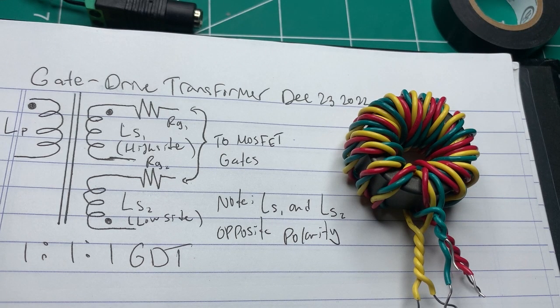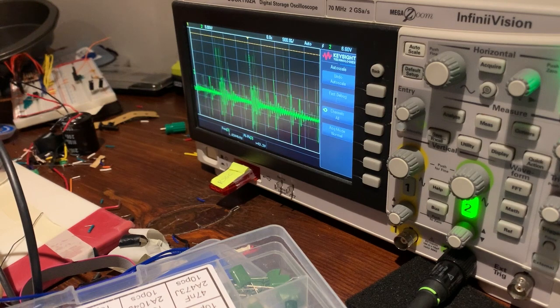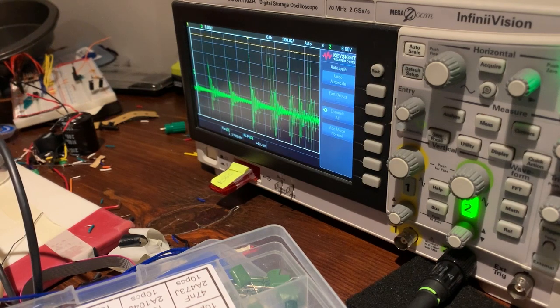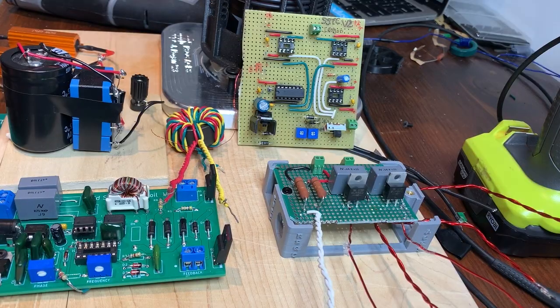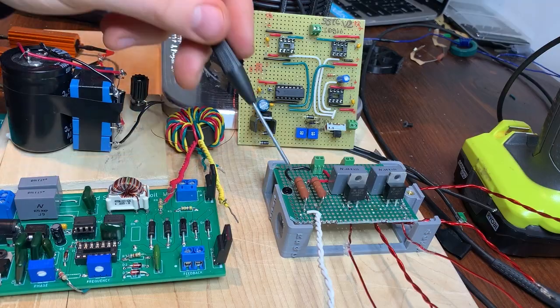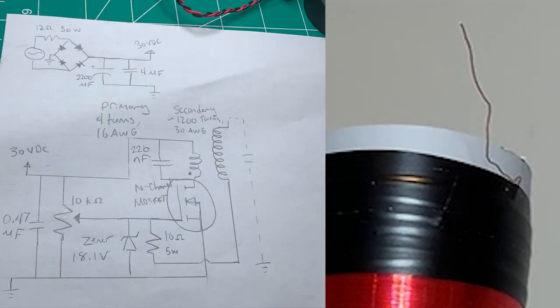Unfortunately, this device was extremely problematic in both driver circuits. Here you can see the signal from the first tiny gate drive transformer, and it's complete garbage. The second one, which I wound myself, produces a better waveform. Unfortunately, neither of these drivers worked, and the only sparks I ever produced were made using the Slayer exciter circuit